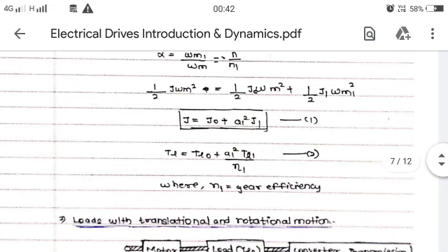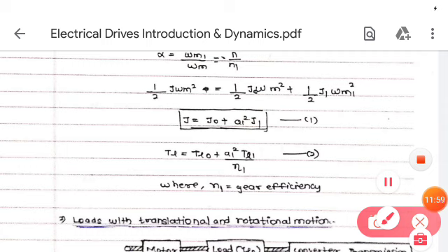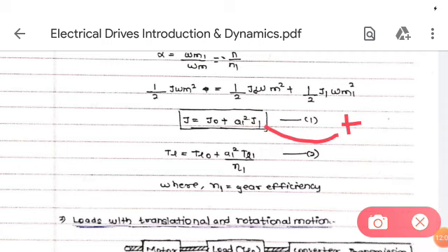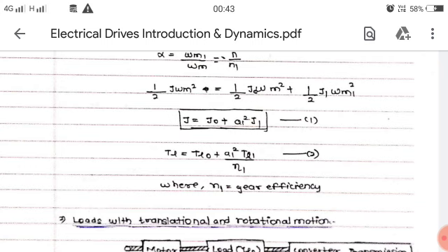So to this equation number 1, just add here plus that equation. So that becomes a system having one load directly coupled to the motor, another load through gear, and another load through rotational to linear motion transmission. Similarly, the term of torque can be added here and you can calculate the equivalent torque. So as simple as that. So I hope you understood this, how to calculate effective inertia and effective load at the motor shaft.